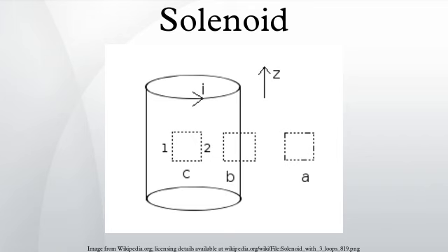This is a derivation of the magnetic flux density around a solenoid that is long enough so that fringe effects can be ignored. In Figure 1, we immediately know that the flux density vector points in the positive z direction inside the solenoid, and in the negative z direction outside the solenoid. We see this by applying the right-hand grip rule for the field around a wire. If we wrap our right hand around a wire with the thumb pointing in the direction of the current, the curl of the fingers shows how the field behaves.